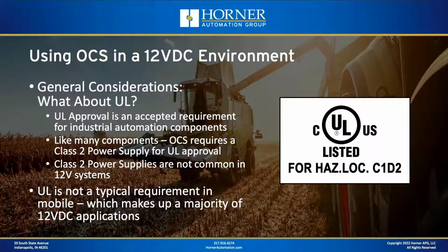And what you'll find is that Class 2 power supplies are not common in 12-volt systems. I think I've seen one Class 2 power supply for DC, and it was not compatible with 12 volts. It required 24 volts on the supply side. But the good news is that in the mobile arena, which is the lion's share of the applications, UL is not a typical requirement. So the lack of UL, because of a lack of a Class 2 power supply, will not be a problem nearly always.